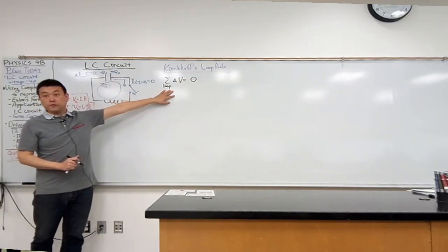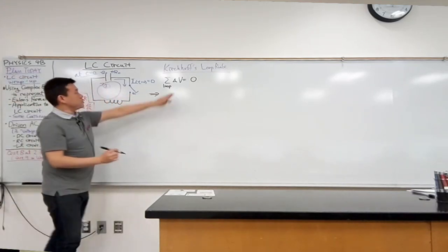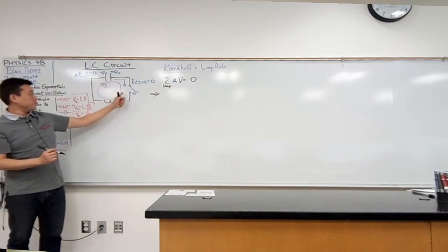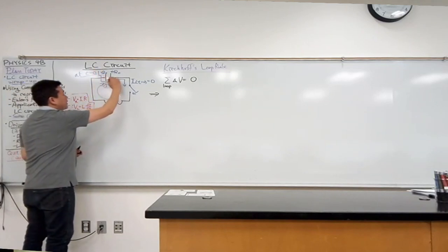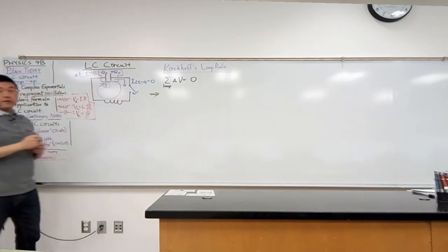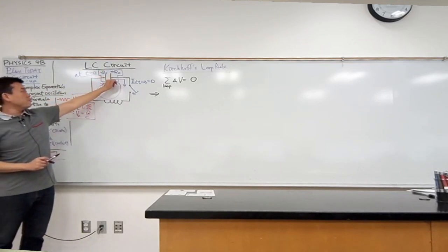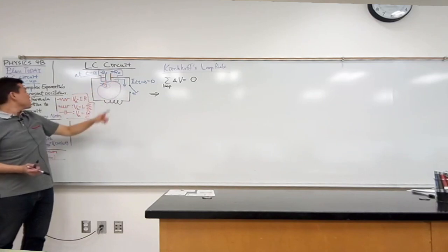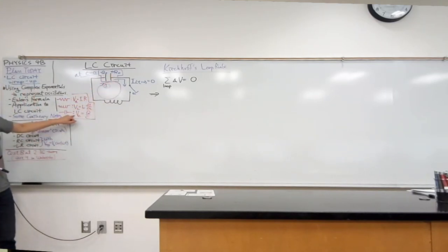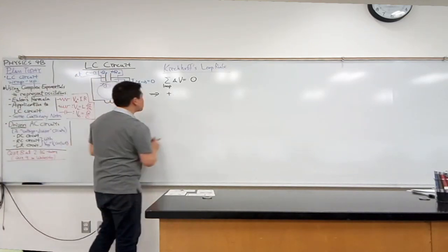This will continue to hold true for all the circuits that we are analyzing. So let's write out all the changes of voltage as we go around this loop. So I specified my initial charge this way. So I will define my sense of direction in a way that's consistent with this. So as I go across the capacitor, do I gain or lose voltage? Gain voltage, right? I'm going from the negative to the positive plate. And the amount I gain is here. So as I go across the capacitor, I'll gain plus, and I'm going to write charge as a function of time.